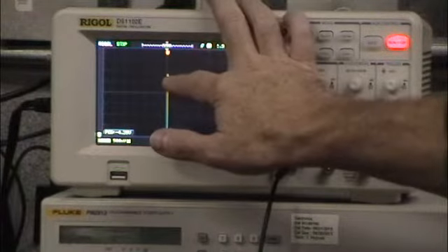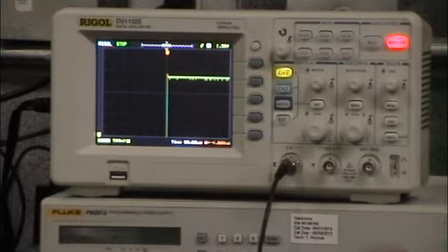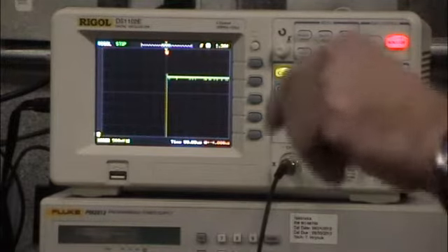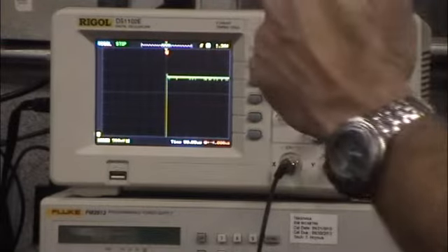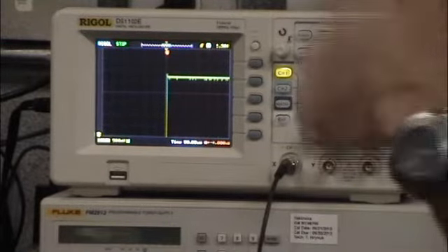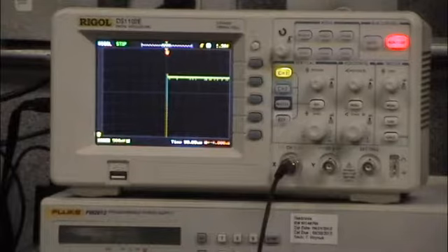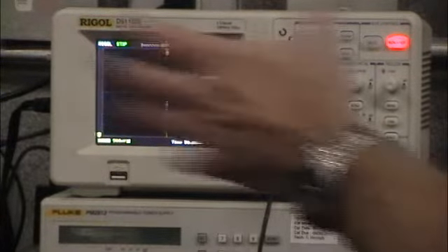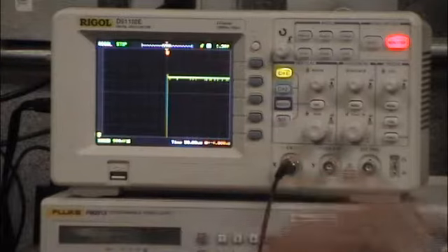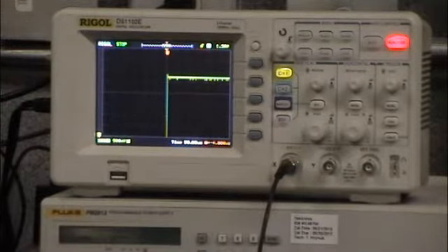See that little overshoot right there? That's in the noise on this. That is from the inductance in the tracks. So we talked about how when you've got an inductor, it doesn't want to let current stop, but if you suddenly take away the path for the current to go, it's still pushing current. Ohm's law, the resistance just went to infinity, V equals I times R. R went to infinity, current stayed the same, voltage goes to infinity. The reality is there's nothing that's infinite here, so it sort of pans out. And the inductance is really crappy, so it's a function of how much inductance is there.